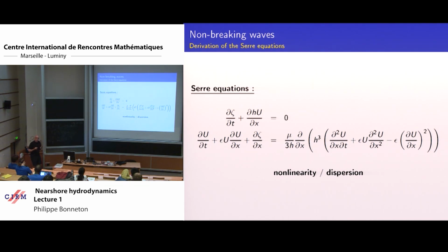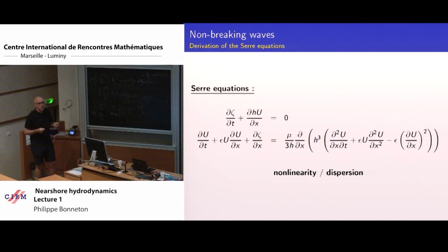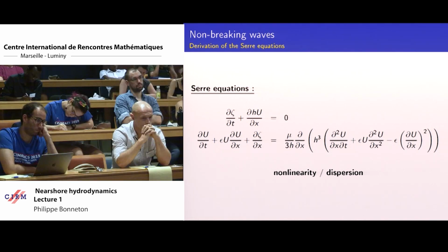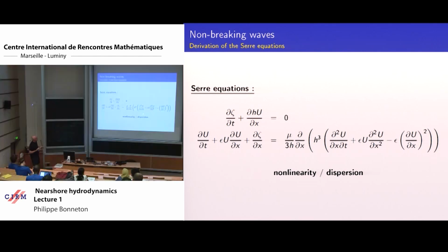But for swell, for wind-generated waves, mu is small, but not so small. So you need these non-hydrostatic terms. And this term plays a very important role. In particular, you remember I spoke about the dispersive effect. In fact, this term controls the dispersive effect.